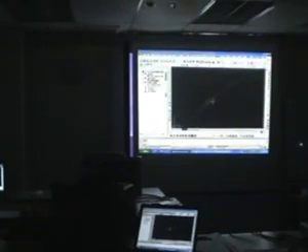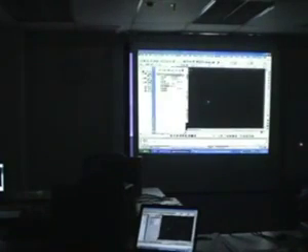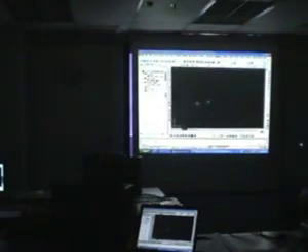And the text, right? Let's say you need to move the text. I just select this contour line. Just to point out to you, this is a civil contour object, not a polyline like in AutoCAD, not just a 3D line or anything like that. This is a contour object. You can see that the marker has also been selected together with the contour line. If I need to reposition this text, maybe sometimes in a drawing you have the text overlapping the boundaries of your platforms, for example, you can just click on this marker and drag. I'm going to zoom out. You can see no matter how far I drag my cursor away from the contour line, the text still follows the contour.